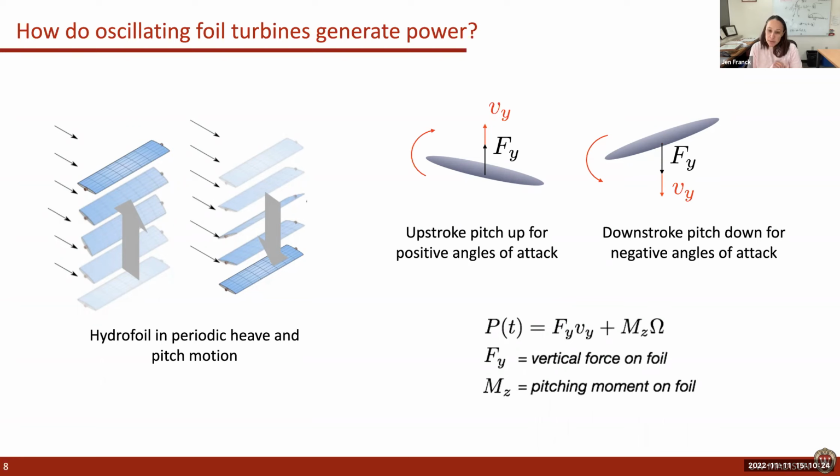And you can think about also getting power from that pitching moment on the pitch reversal at the top and bottom of the stroke. If your moment is in the same direction as your angular velocity, you can generate power from that as well.